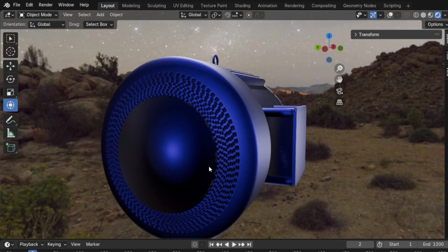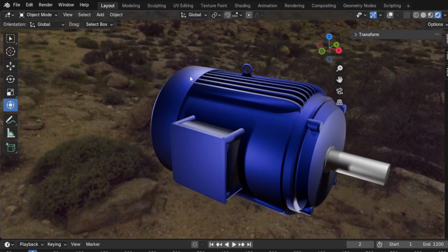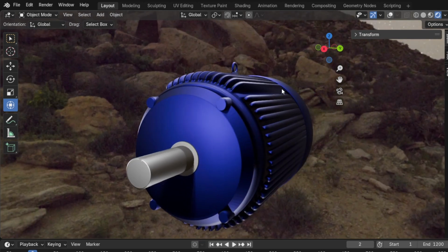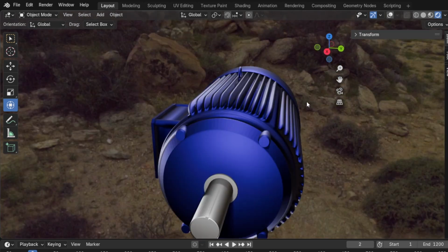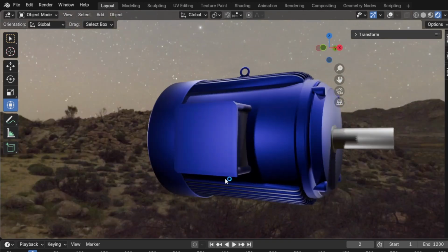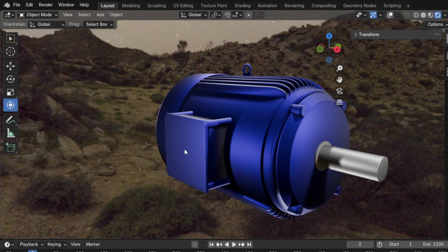All the way back here, usually there's a fan that attaches to this side of the shaft that helps pull air, or push air, through these vent holes. That air gets forced across these little rib sections right here, and these ribs increase the surface area so the motor can dissipate heat more effectively. We all know that motors don't like heat, and a good way to increase the longevity of a motor is to decrease its operating temperature, right? That's the thinking behind these little ribs right here.